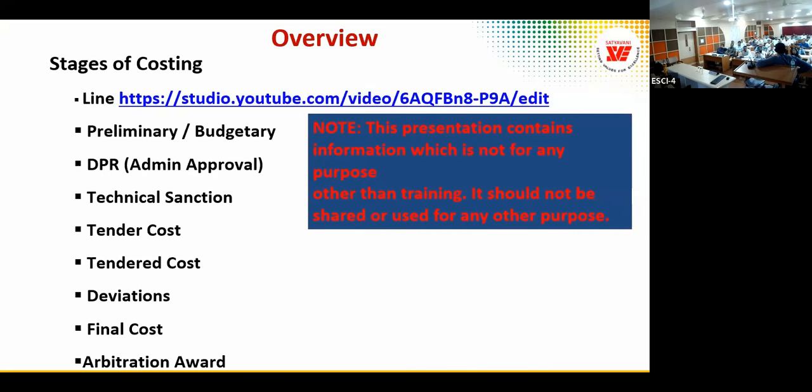So this is the experience we have when it comes to technical sanction. But ideally, it has to be the same. Of course, this is an exception; not many projects have so much variation between market rate and DSR or SSR. In fact, DSR is fine when the market variation index is available for that location. Some locations don't have a market variation index, where we have to do a real market study and come up with the variation index. And if the department accepts that, then it's fine.